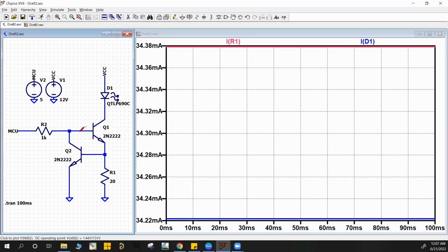And because, like I said, in most cases the base current is very negligible, a very small amount, when you're dealing with amps of current it doesn't really show up. But because we're dealing with a small amount of current in this case, you could see the difference. But yeah, that's pretty much it. And then what we said is, let's just test, right? The idea was if we change VCC to any voltage, the current through this LED must stay the same. Let's see if this is the case.